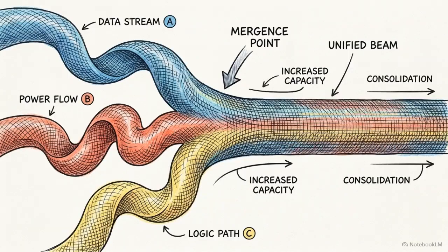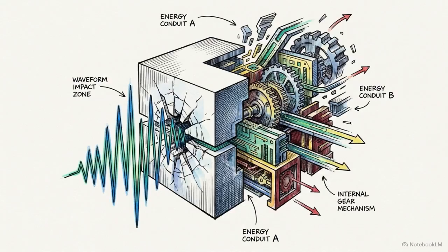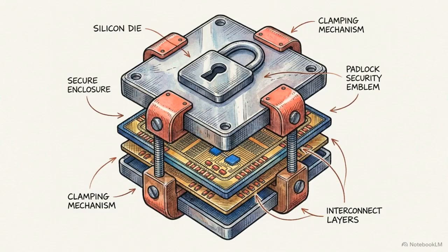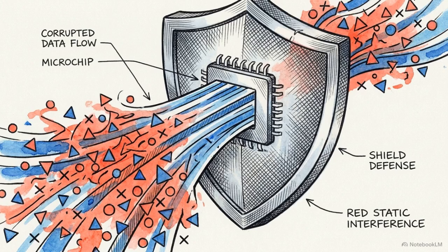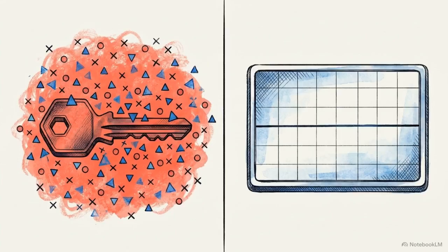By combining the outputs of these 3 distinct encoder blocks, the trunk flattens a vast, noisy time series capture into a unified, mathematically dense representation of the chip's power signature. The hardest problem GPAM faces is cryptographic masking. To prevent side-channel attacks, secure chips inject random mathematical noise into the sequence, blinding the secret scalar with a random mask so the power signal looks completely decoupled from the actual key.